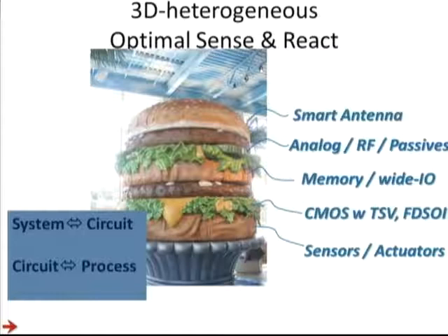One is the antenna and the power amplifier for the transmit stage. Those have in the past been designed separately, and the fact that you can design them together, co-optimize them and model them together is leading to a lot of savings in power and performance. Another reciprocal optimization is the antenna with the LNA for the RX stage.